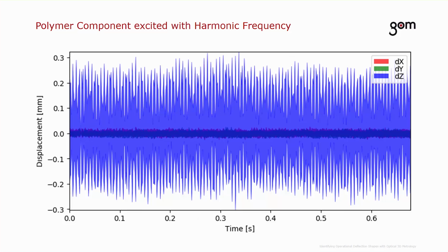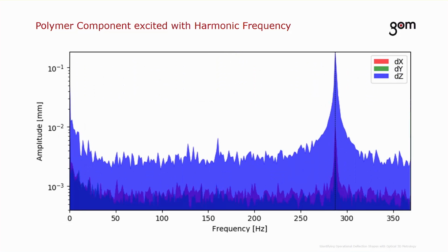We use the displacement information over time that we gathered with our RMS system to feed it into a frequency analysis. So here this was the input file, or in the diagram you can see the envelope curve of all these displacements that we measured on the measuring points in all three spatial directions, and this was exactly the information that we handed over to the vibration analysis software tool to get our frequency response curve.